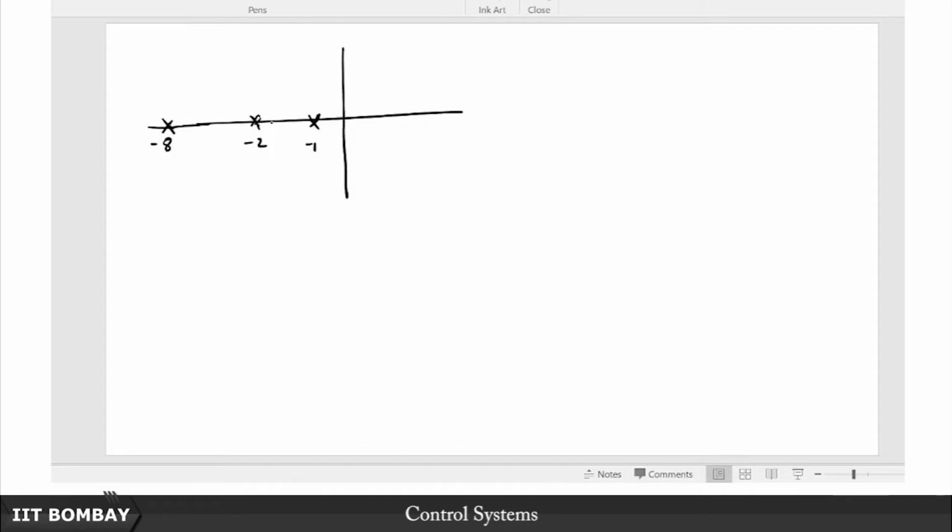Another point I might have missed: recall in an earlier lecture we said that when you have additional poles and zeros and want to approximate a second order system, you don't just drop the poles and zeros in the open loop stage. You close the loop around it, and then see if it meets the 5 times criteria.